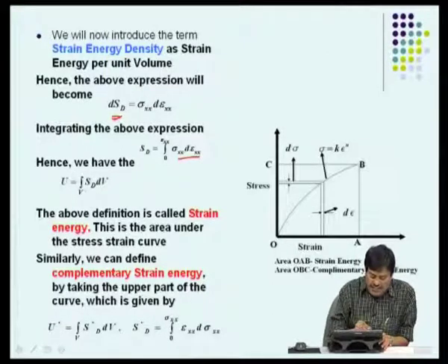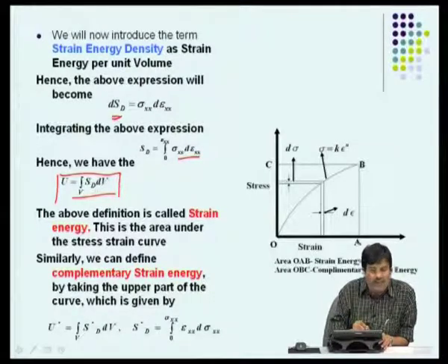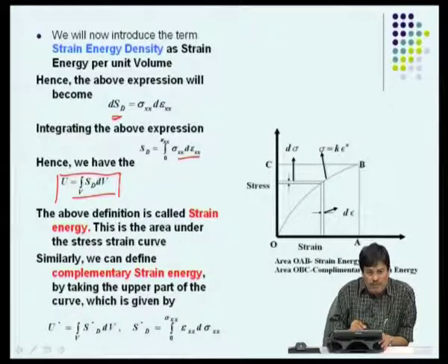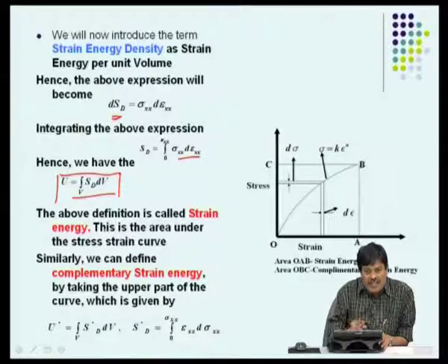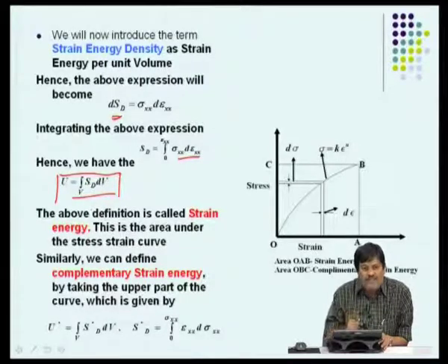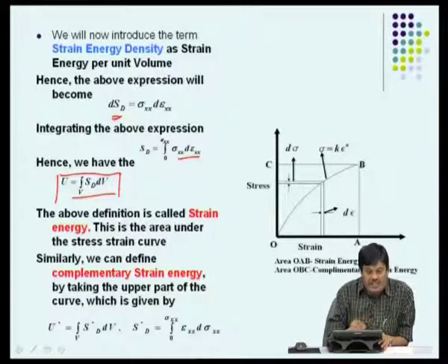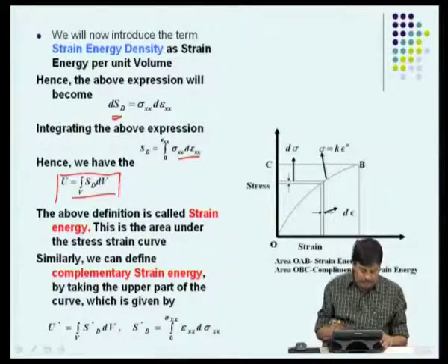So, this is the definition of the strain energy. For this, we have to integrate the strain energy density over the volume, and the strain energy density is a function of the stresses and the differential strains, so we need to integrate this for the strain levels. So, the total strain energy is defined by this equation.